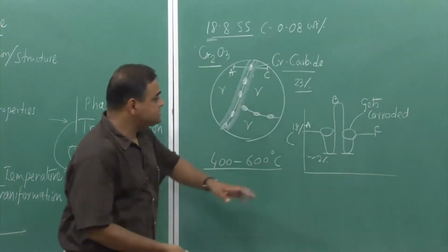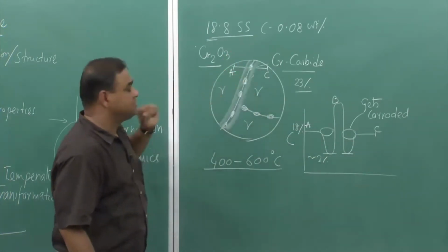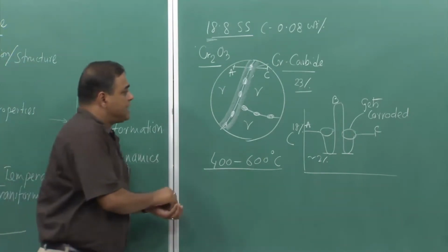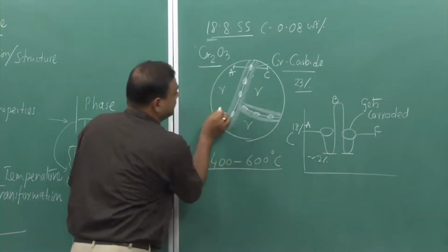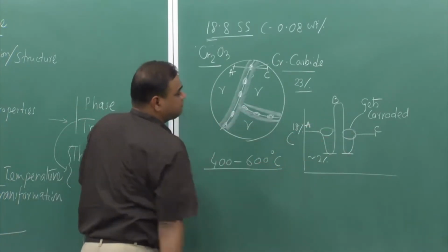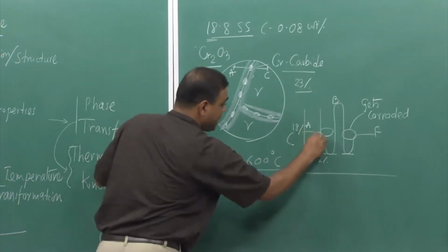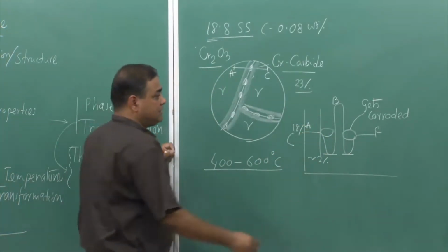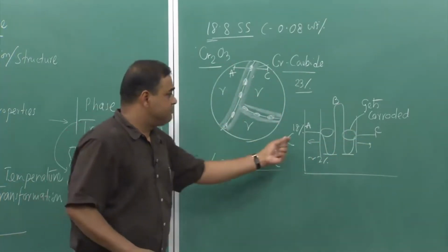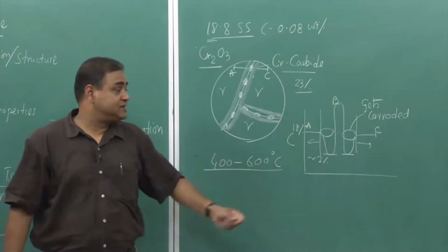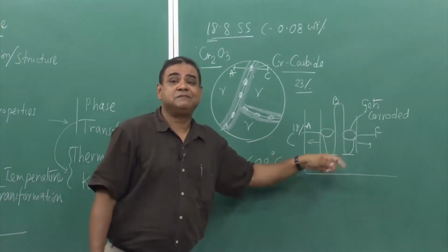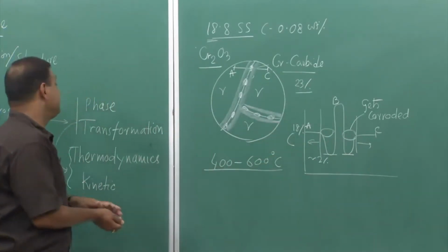So, that means a thin section along the grain boundary gets corroded, and along the grain boundary all the time we have very high corrosion, because away from this particular precipitate zone we have 18% chromium. So, here we have the chromium oxide layer, here we have the chromium oxide layer. So, no problem, no corrosion takes place, but this zone is exposed. So, there corrosion happens.